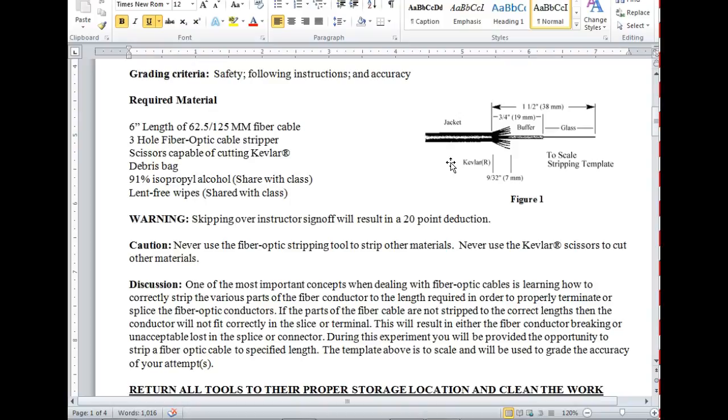But we never actually do this on a real cable, because what probably just happened? I probably broke the glass. Not inside the jacket, but I probably broke it inside the tight buffer. But it's no big deal. The tight buffer is what's actually holding it in there. I can't break the tight buffer. But now we can play around with it. So that's what I wanted to show. We're dealing with a real short length, and right now if you tried to strip it, it's just going to pull out, and your strip length will keep changing. Right? Okay, that's what I wanted to show you.